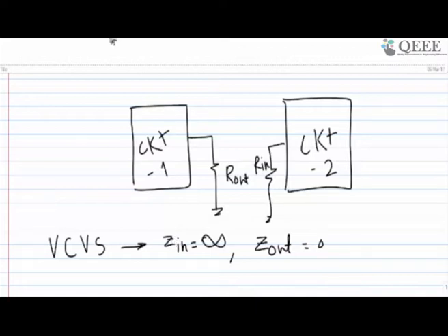These play important roles when you are trying to connect circuits together. So I'm using the Y parameter because I can see the input impedance and the output impedance of any circuit, and that is easier to calculate because the Y parameter is I by V. So it's very easy to find out how much impedance or admittance is available in my circuit.